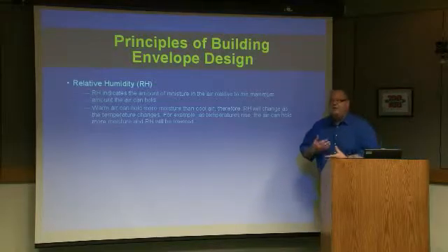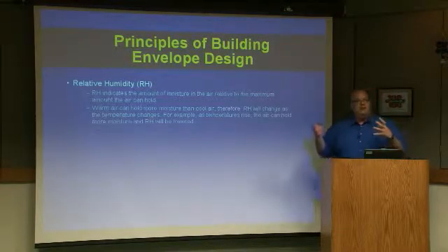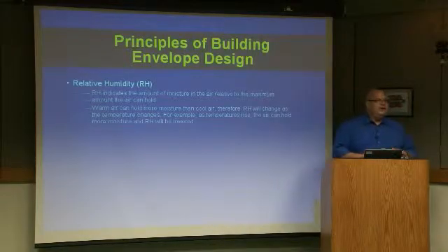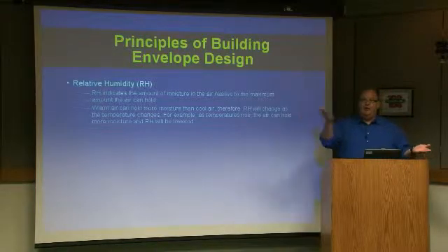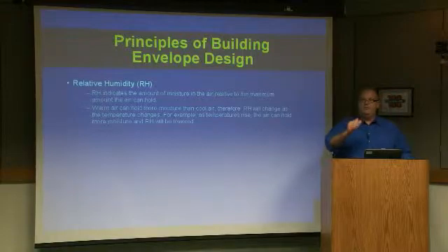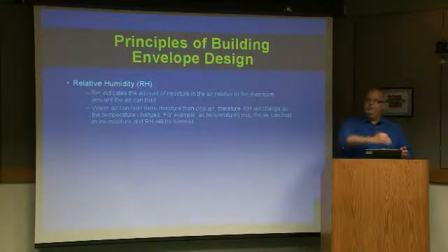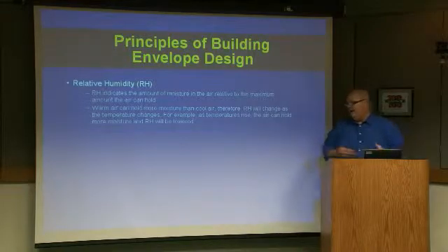Now this becomes very, very important towards moisture management, because water vapor drive, the movement of water vapor through your building assembly, is a reaction to the difference in pressures across the assembly from high pressure to low pressure. Nature always goes from high to low, and the resistance of the layers in between will control the rate at which that vapor flows through. Now, that's a very straightforward way to calculate the rate at which the moisture moves.